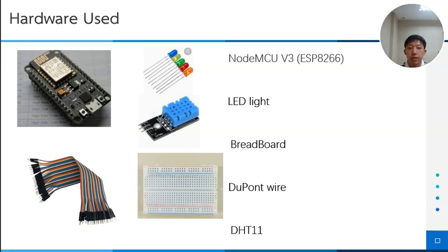What is displayed on your screen is a physical connection diagram, which clearly marks the connection relationship between the key pins of the ESP32 development board, such as 3V3, ground, and other hardware. Following this diagram, you can complete the hardware assembly, laying the foundation for subsequent software debugging.